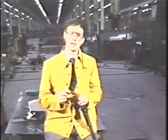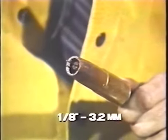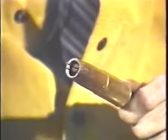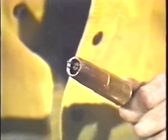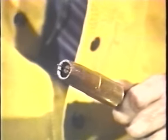Can you remember where we set the contact tip for short circuit welding? Slightly outside the nozzle, keep the wire stick out short. Spray transfer is the exact opposite. We should set the contact tip slightly inside the nozzle, maybe about 1/8 of an inch down inside the nozzle. Two reasons for this. One, we need a longer stick out because we no longer short circuit. And the other reason is we want to protect the contact tip from the intense heat.